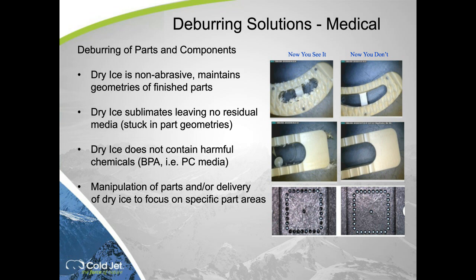Sometimes you bead blast, use a variety of different things. Depending on the geometry of your medical device, you may end up with part of your blast media stuck in your medical device part, and you've got another operation to get it out. Depending on what you're using as a media, like polycarbonate as a blast media, that has BPA in it. You can cross-contaminate medical device parts with some of the media that you use. Dry ice does not do that. It doesn't leave any harmful residues behind.